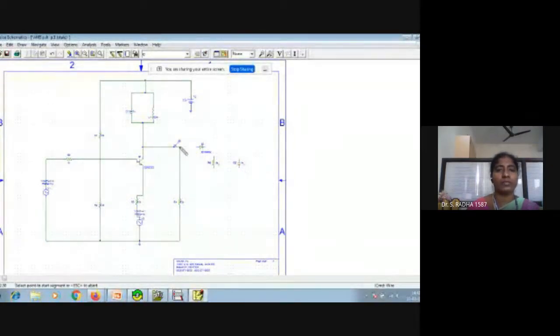Now I will do the connections. I have to connect from this output point. I am giving input to the envelope detector. This portion is the envelope detector. And they are connected to the common ground. Same ground point, I can connect them. Only 3 elements, demodulation is completed.